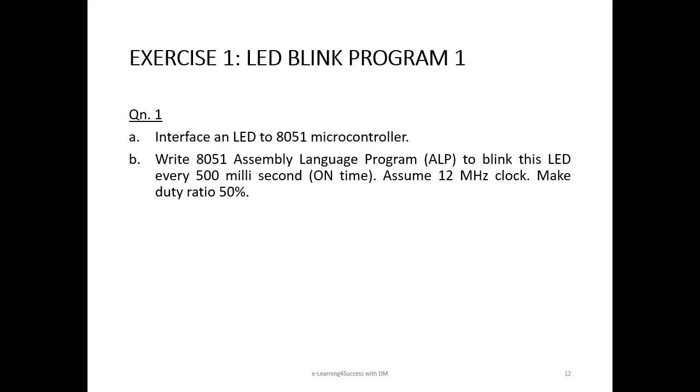The first exercise that we are going to do is to interface an LED to the 8051 microcontroller. Then we will write an 8051 assembly language program to blink this LED every 500 millisecond. The 500 millisecond given should be taken as the LED on duration only. Further, we will assume a 12 MHz clock and 50% duty ratio.